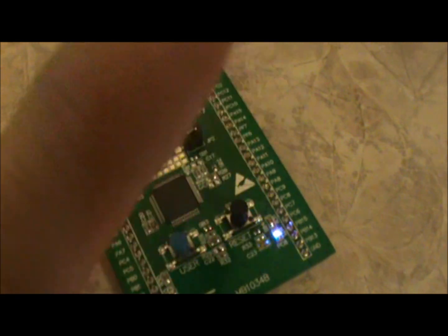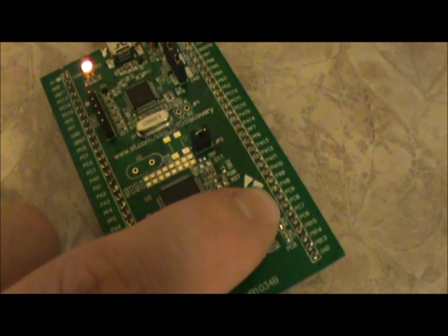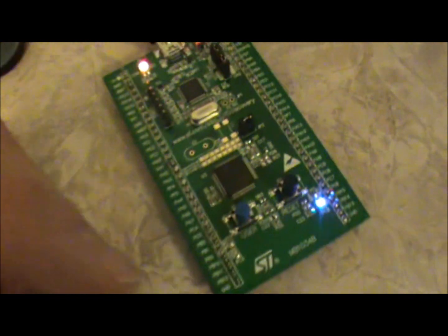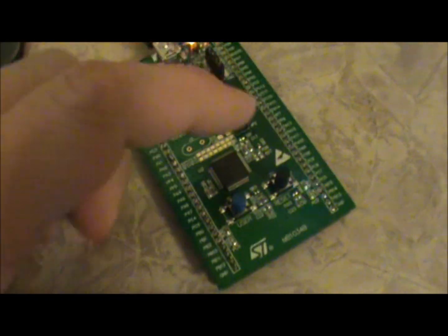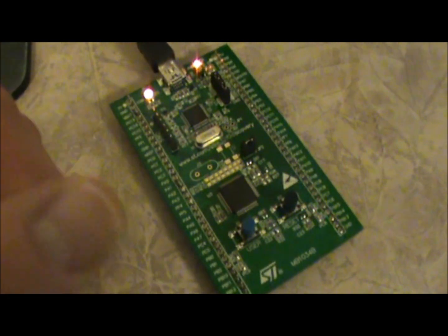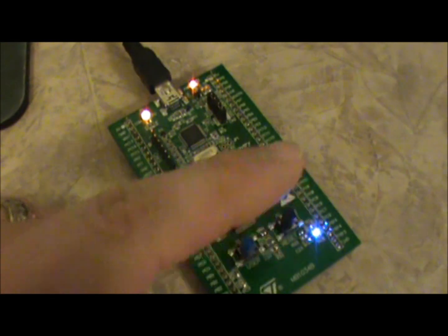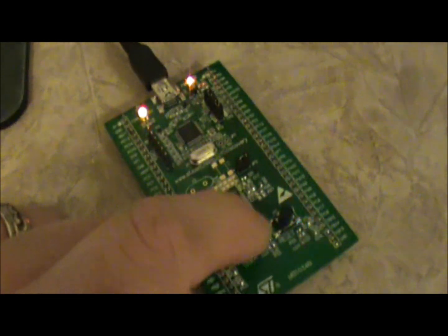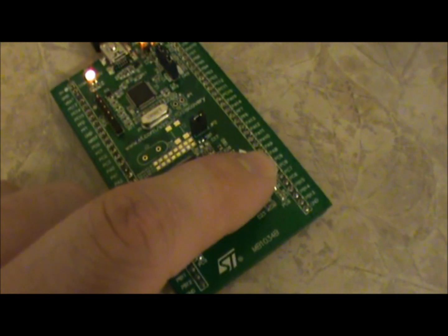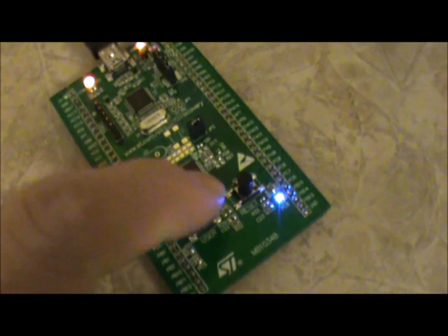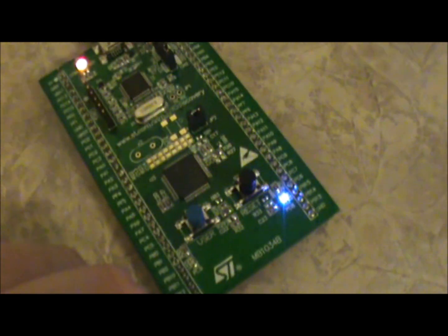Reset holds it in reset, and then clear. So it's the same thing as pulling the mem clear line. They have the reset hooked up. If you watch my first video in this series, I show the schematic off, and you can see how the reset is hooked up. It's basically like yanking the mem clear line. It does a software reset when you push it.